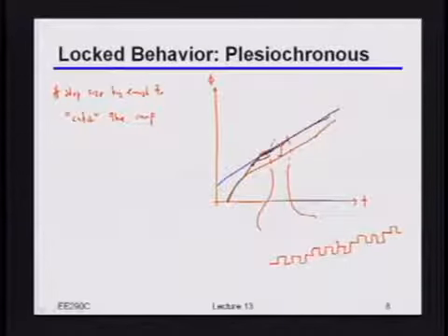Now, of course, there's still going to be the dither around there, but at least the size of that dither is not set directly by the frequency error that you're tracking. You still have to make sure that you can keep up with that ramp, but the good news is that since we're only going after a few ppm, that's usually a pretty easy thing to do. Okay?